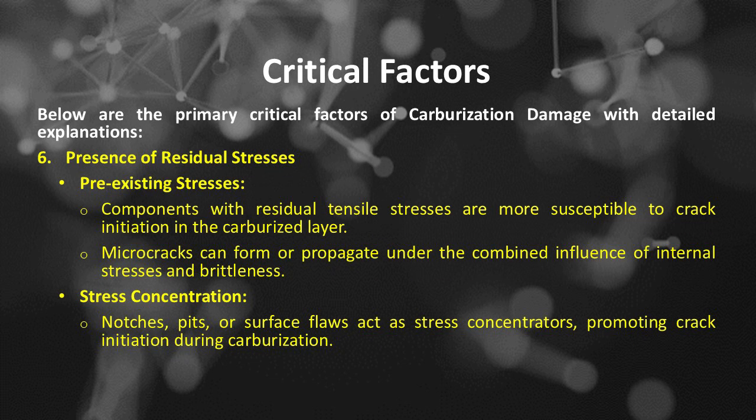Number 6 of primary critical factors of carburization damage with detailed explanations is presence of residual stresses, pre-existing stresses. Components with residual tensile stresses are more susceptible to crack initiation in the carburized layer. Microcracks can form or propagate under the combined influence of internal stresses and brittleness. Stress concentration: notches, pits, or surface flaws act as stress concentrators, promoting crack initiation during carburization.